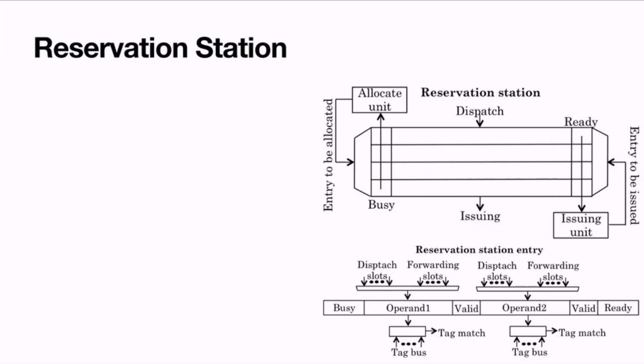Once the multiplier is available, we come to the reservation station associated with the multiplier and see which instructions are ready to be scheduled. Then we pick one of those ready instructions and schedule it onto the functional unit. Here, for a simple solution, we just consider the one which came earlier, or age-based priority.